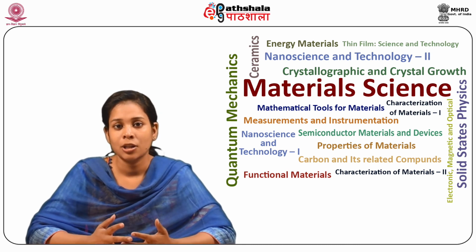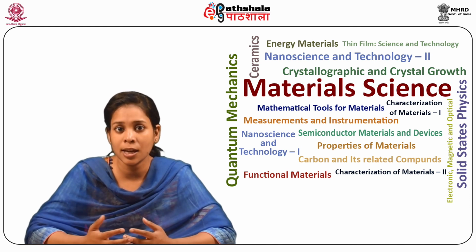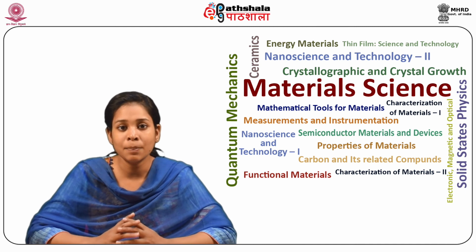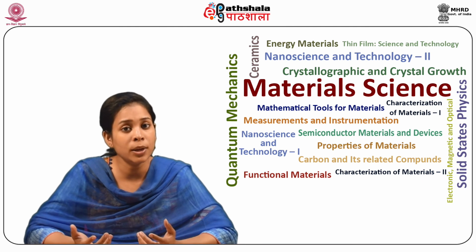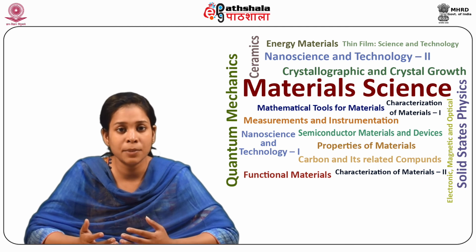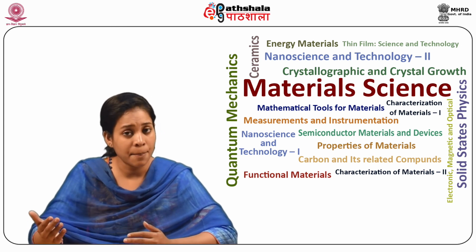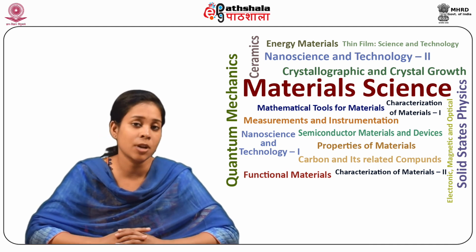These large structural units lead to a higher viscosity of the melt. The units have low mobility and are not able to arrange themselves in a crystalline structure in the limited time available during normal cooling. On lowering the temperature, the viscosity increases rapidly and the material becomes a rigid solid with an amorphous structure.